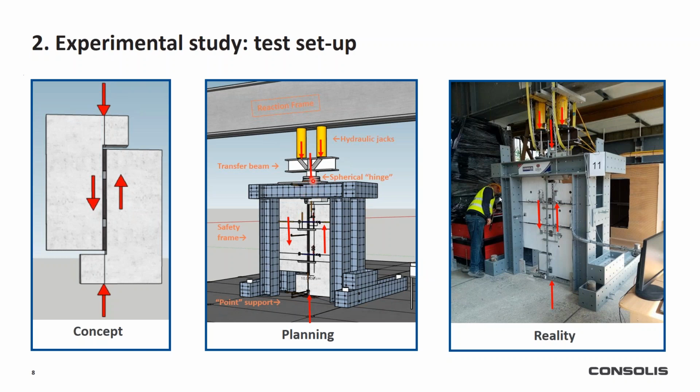It is based on hinged boundary conditions, so the lateral displacements are not constrained for the specimen. So we had a neoprene pad and a spherical hinge and 2 hydraulic jacks that are loading the test specimen in the axis of the connection.